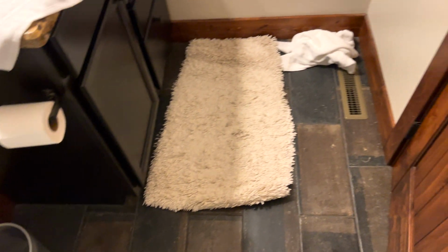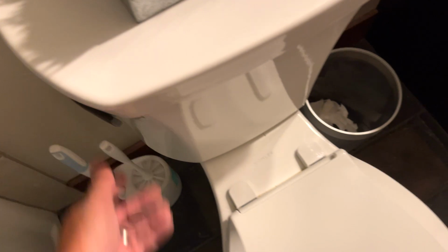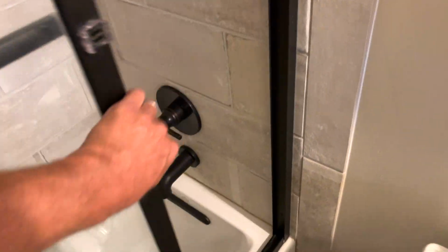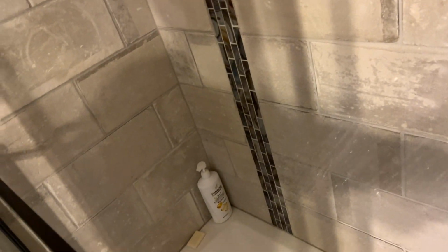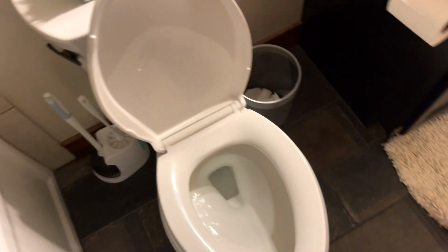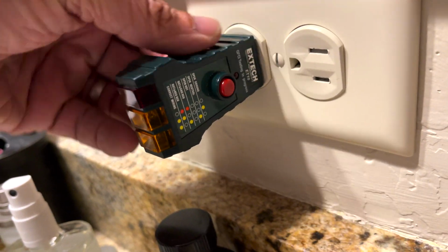And the second bathroom. So this is the master bathroom. We'll do the same procedure, hot and cold water. Flush the toilet a couple times, make sure it's secured to the floor. Look for leaks at the valve and at the fixture itself, how it's secured. Turn on the tub, hot and cold water, drain, shower, functional flow. The shower surround and the tiles look all good. Look for plumbing leaks at the sink, at the pipe, and at the valves, and at the cabinet. Test the GFCI. There's a tester here. That works.